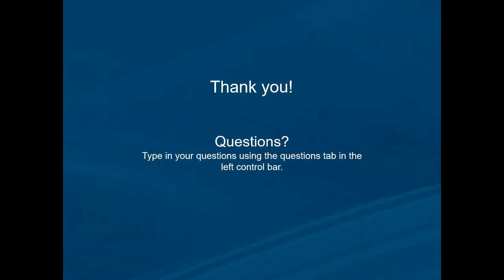Another question on steam generator tolerance: how's an STS? STS, again, depending on your airstream conditions, has the ability to do plus or minus 5. I wouldn't recommend much tighter than that. The thing about an STS is you're using a steam control valve to meter the steam that goes into the heat exchanger, and therefore boiling off the amount that's going into the airstream.